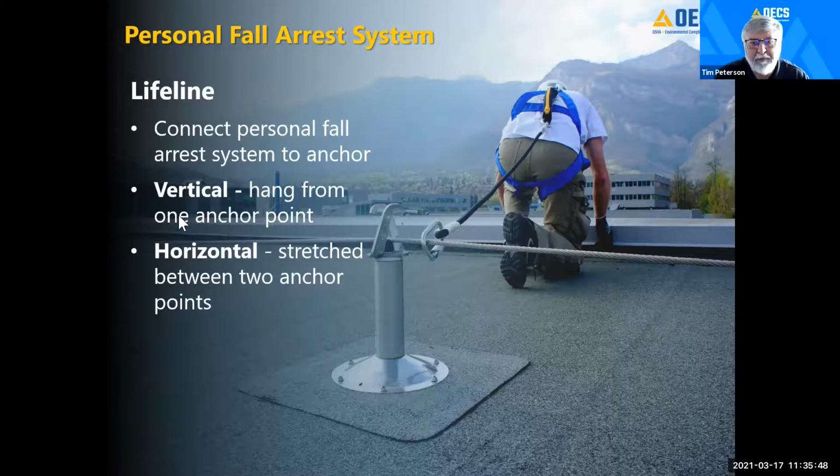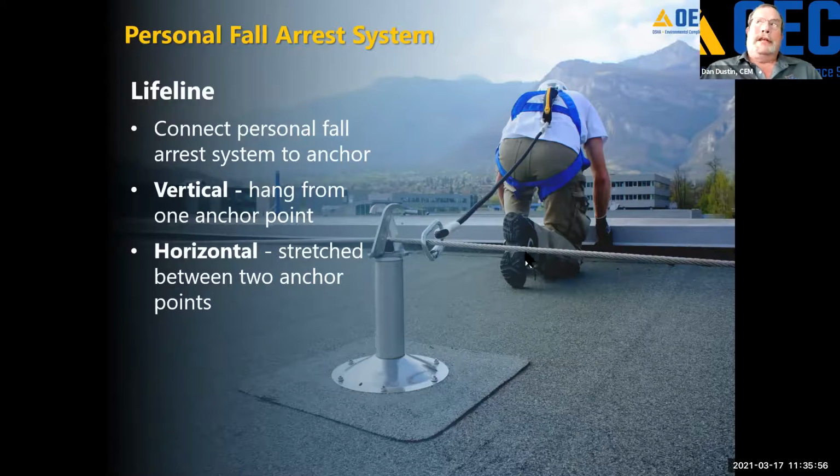Dan, what's the minimum diameter cable allowed for this lifeline? Depends on the manufacturer, but typically I'm not going to see anything less than 1/2 inch. I don't think I've ever seen one less than 1/2 inch. Now, what you may find is that you will have guardrails run around a perimeter. For example, the iron workers have put up their cable guardrails around a perimeter of floor. And if they leave the site and sign over that guardrail system, that can be smaller than the fall arrest anchor, because it's not designed to be used as a fall arrest. It only has to withstand 200 pounds.